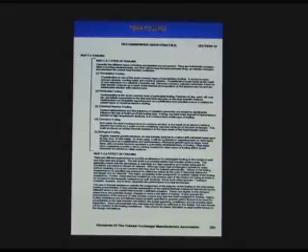We have particulate fouling, sedimentation. We might have sand or other things that are entrained in the stream which will drop out and coat out the tube. Chemical reaction fouling, another issue. Corrosion fouling for iron oxides, we might have that in sulfur units where we might be forming iron sulfite, which could potentially coat out the tubes along with molten sulfur.